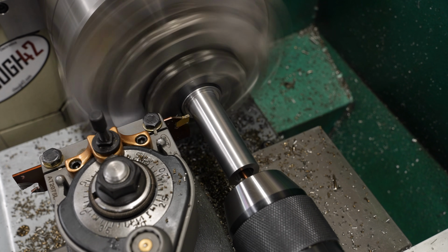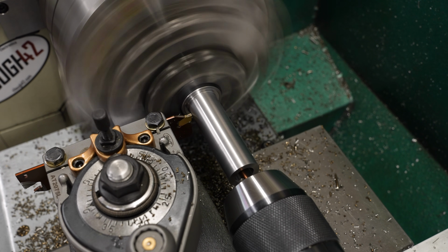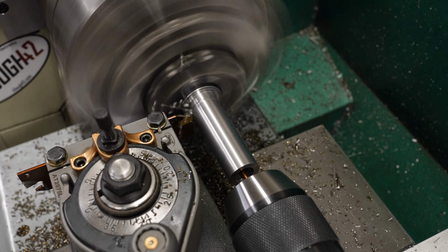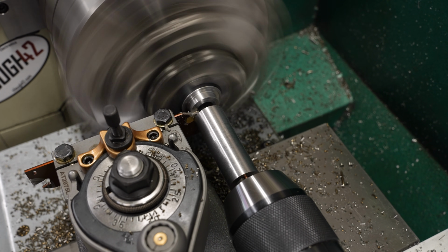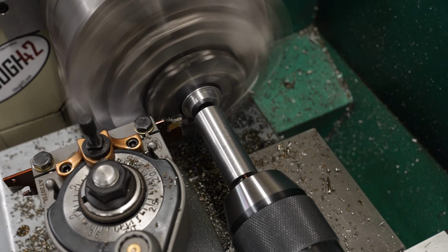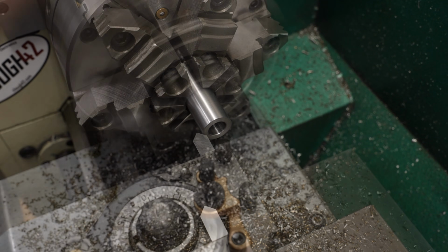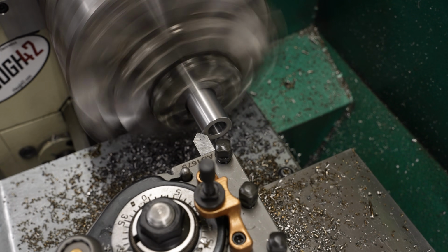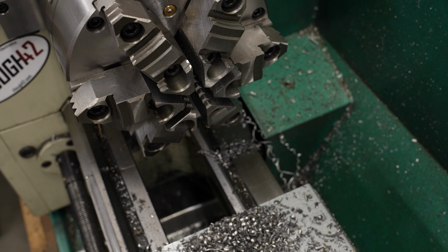And as you've seen me do in previous videos, I'll bring it in, just touch the part, and as soon as it hits and starts to make a chip, I'll just start cranking and we'll push it through. And you can see the chips in this 1144 break beautifully with the parting tool. Just flip it around in the chuck and use a chamfer tool to put some tiny chamfers or just deburr the edges. And that part's done.